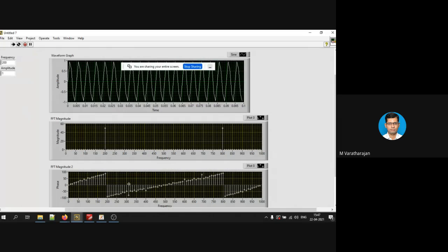You can see from FFT that even though the sine wave is not exactly sine wave, but if you see in frequency domain, even though I am calculating fast Fourier transform, the signal I have given is a periodic signal. So therefore, this FFT will look like a Fourier series. Okay, this is a single frequency component. So exactly at my frequency axis, I have maximum value. If you calculate Fourier series for this signal, it will be similar.